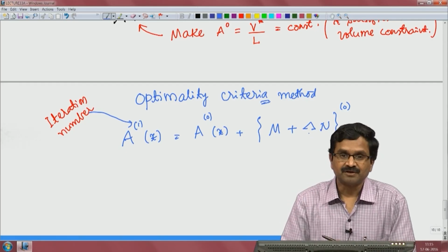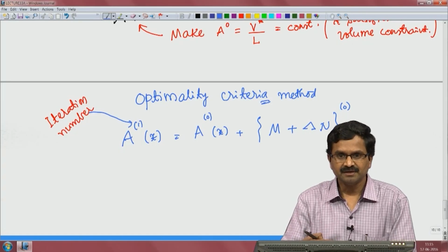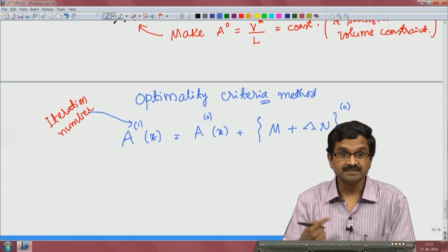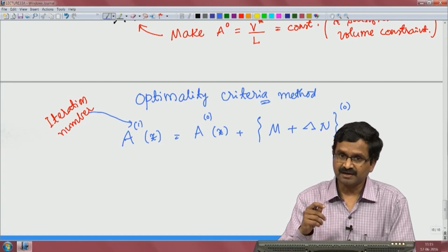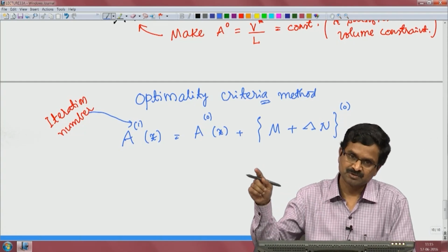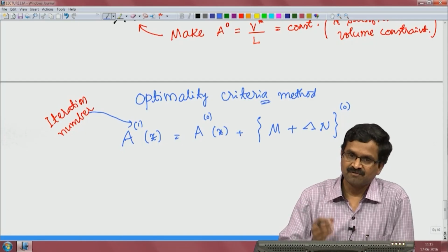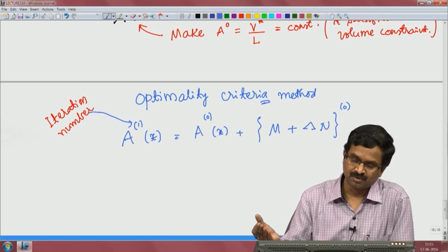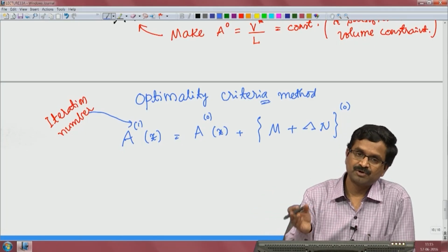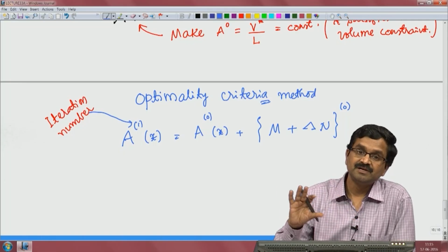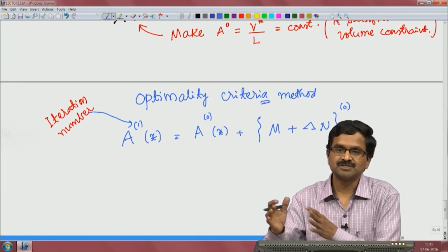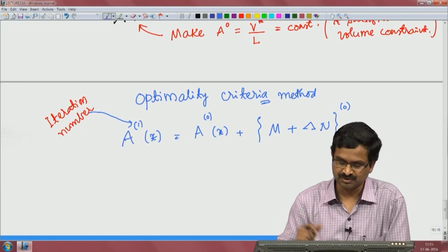There is this lambda that we do not know, but for that we have the volume constraint, which is active by the way, because we got lambda equal to E I W double prime square, which is the design equation. If lambda equal to 0, W double prime equal to 0, and if put in the equilibrium equation, that will lead to a conflict, that something 0 plus q equal to 0 or minus q equal to 0, right.